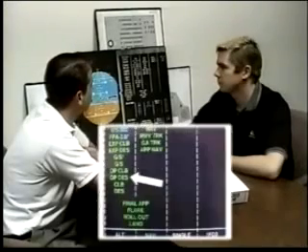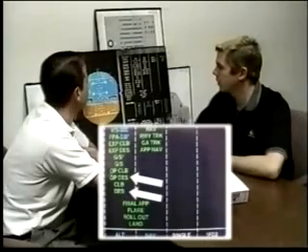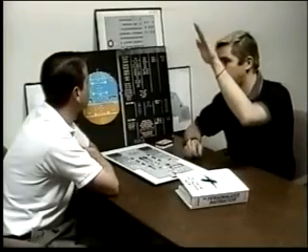Then what would be the difference between open descent and descent? Actually, it's a real big difference. You'd think that if these were similar, these would be, but they're not. Open descent is similar to the open climb thing. Open climb means climb at whatever speed I have commanded. Open descent means descend at whatever speed I have commanded. Descent, though, doesn't really mean that. It means follow a VNAV path. And VNAV in Airbuses is very different than VNAV in Boeing.